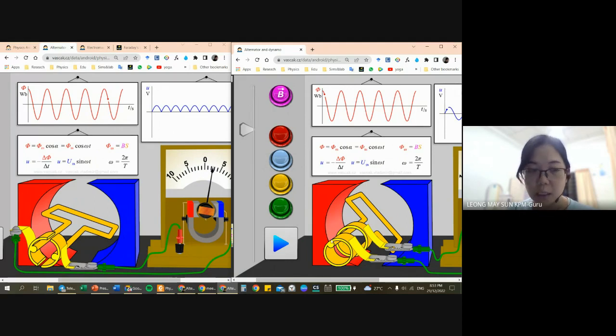How can I see the difference? Because for direct current, this is actually called a commutator. You've seen this in the first part of electricity inducing magnetic field. This is a commutator, and it will produce a direct current out. A slip ring is two rings, and the carbon brush is always touching the same ring.